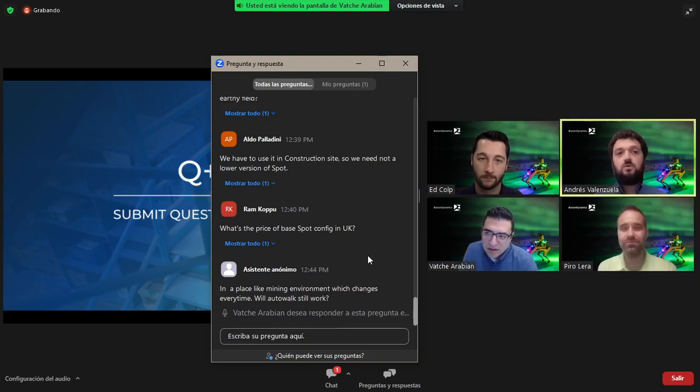But as far as getting around obstacles while executing those missions, that is all happening live and based on the sensor data. So it uses the map to tell which hallway to go down, but then as it's traversing the hallway, it can see, oh, someone left a desk chair here, I'm going to go around that. Obviously, Spot doesn't know it's a desk chair. It just knows that there's something in the way. But that doesn't need the map. That's happening live. Even if you were teleoperating the robot with the tablet and you try to drive it into an obstacle, it won't walk into the obstacle.